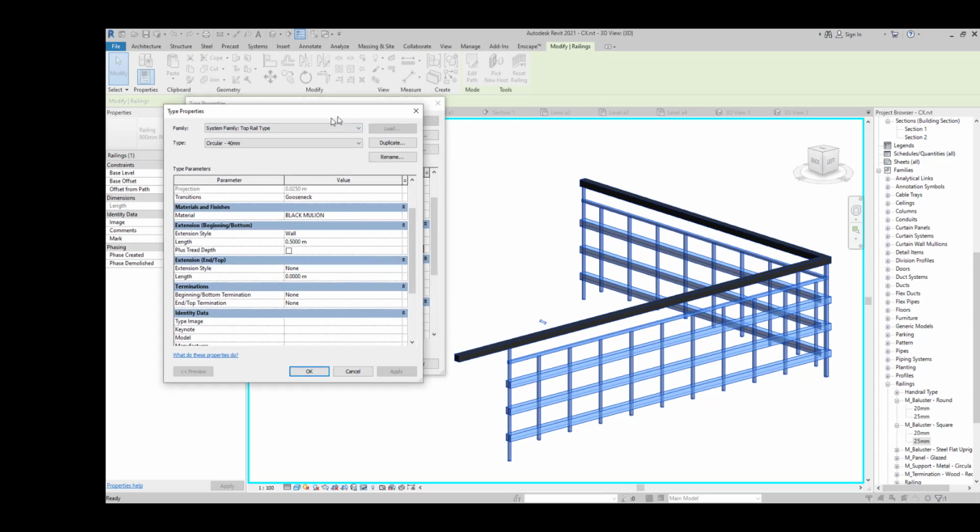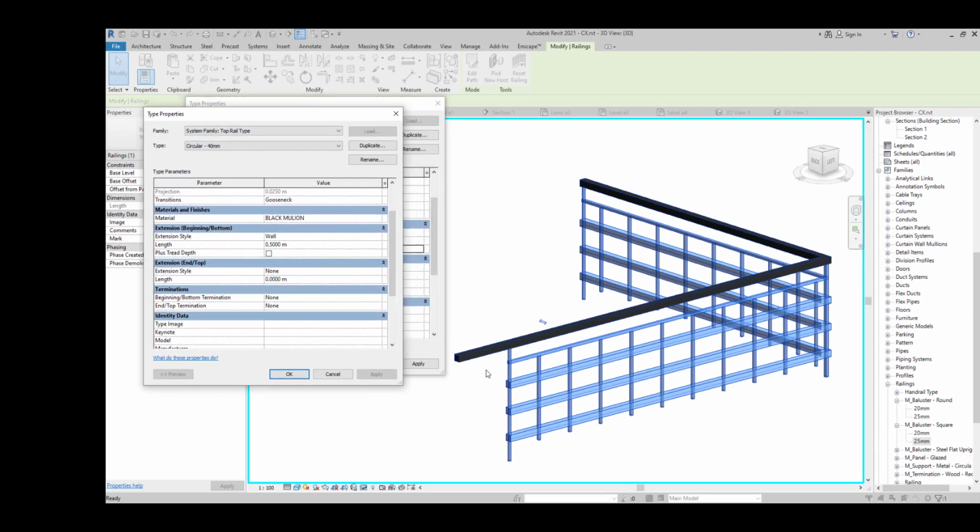You will see your element will continue by your wall, and you can change it, for example, to the floor as well. It's going to continue by 50 centimeter distance to the floor. You can change it to the post. It's going to change the location and continue to the post. You also have these same elements for your end: wall, floor, post.